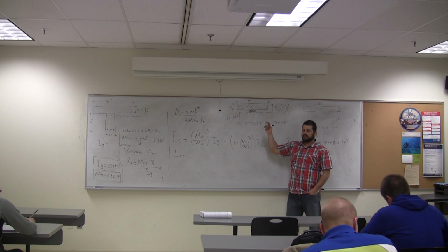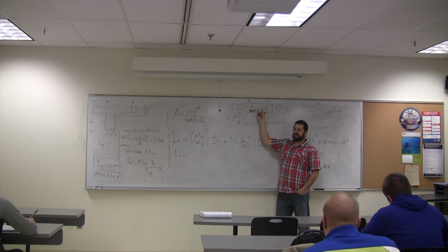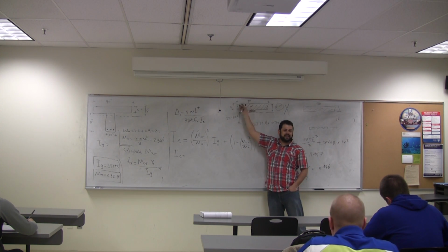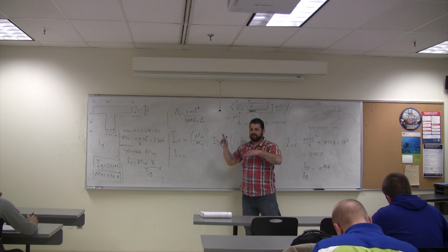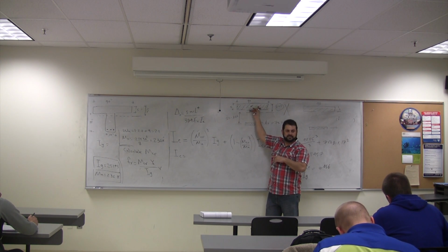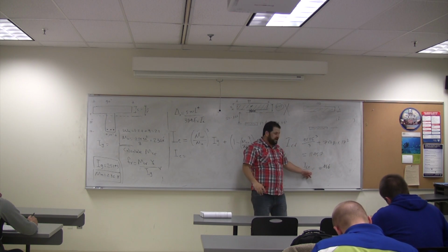You know why the analysis before did not work? The only problem with the analysis is this: we are assuming this one is away from the neutral axis, and this is a huge compression area. The other component of it, which is AD squared, gives us a big number, which is not a real number. Okay? So that's your I crack.